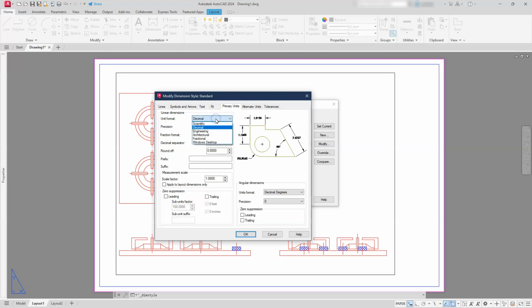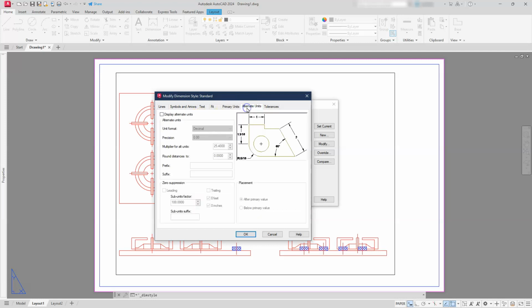So instead of using my normal inches things, let's go ahead and use fractions this time. So let's put it to a more practical approach, is what we're going to see here in the United States. So if I want somebody to measure this out in fractions, I want my fractions not to be horizontal, not to be diagonal. I just want them not stacked. So I'm just going to leave them spaced out this way. My precision is set at a 1/16 of an inch, which is pretty common if I'm going to make this kind of part. Then I'm going to go to my alternate units.